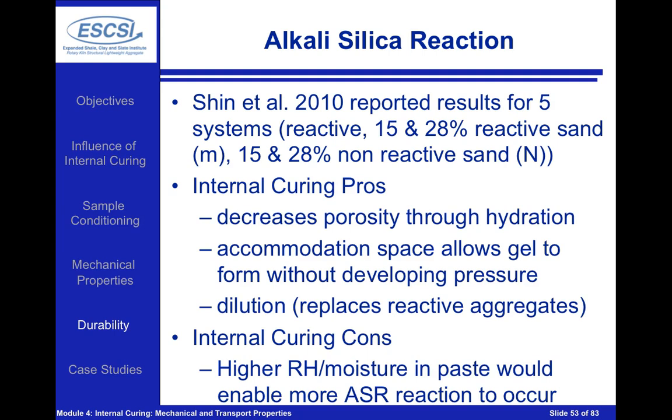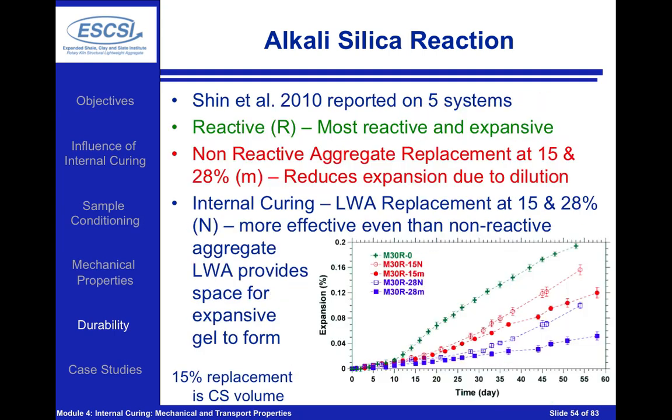One of the cons in this case, or one of the negatives, would be the lightweight aggregate itself is providing more moisture. That moisture would essentially be present for the ASR reaction to occur. So if we look at some examples here, what we can see is 5 systems that were measured and reported on by Shin. And what we're looking at here is a reactive system.